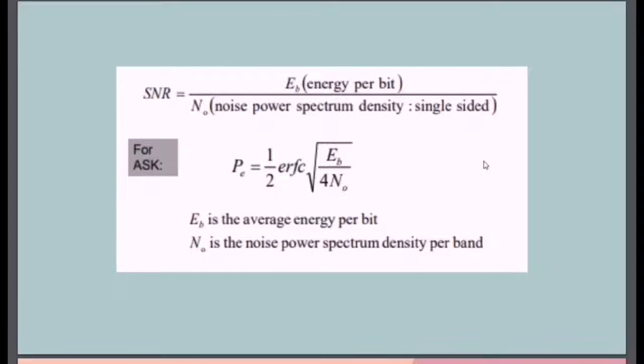Okay, noise or error in a digital communication system is measured using bit error rate, BER. BER is measured based on the difference between the sent and received bits in period T. Normally, the BER will depend on factors such as the modulation technique and SNR, as shown in the figure.